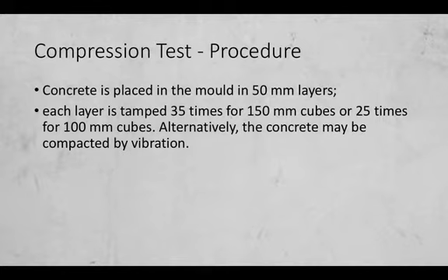It is to ensure that the concrete mixture is thoroughly mixed or is consistent throughout in the mold. And this can also be done by vibration. So you can use a vibrator to ensure that this happens. The surplus concrete is struck off.